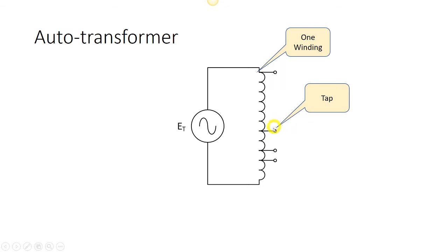It looks like it's a little less than half. So that would be a 50 volt tap. Down here we would have maybe a 25 volt tap and then maybe a 10 volt tap. Okay, so it's just a way to be able to divide up an AC signal without having to build a voltage divider. We can just use an autotransformer to get varying voltages off of a single source.